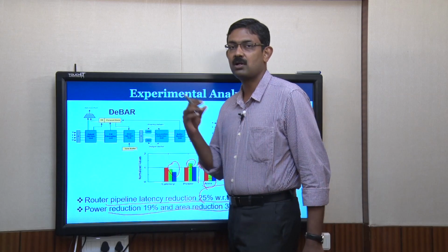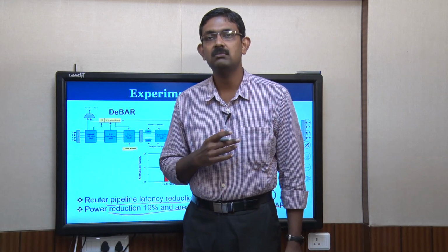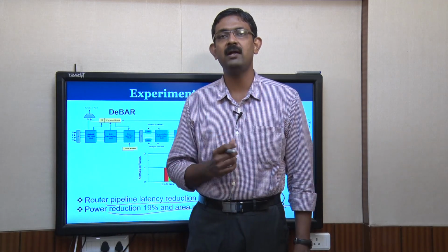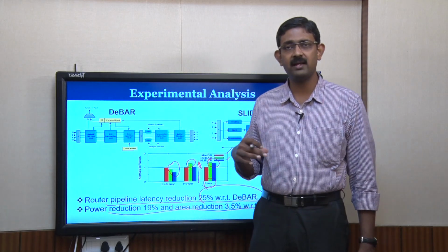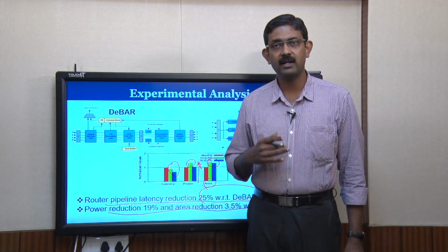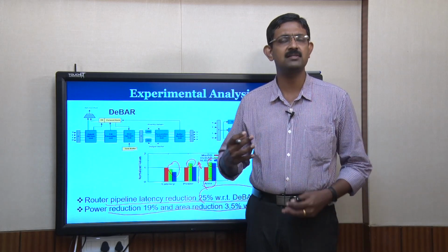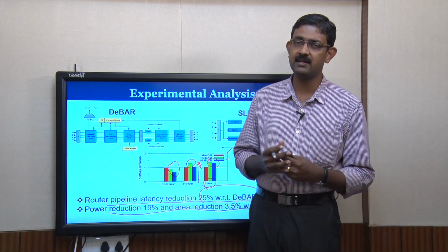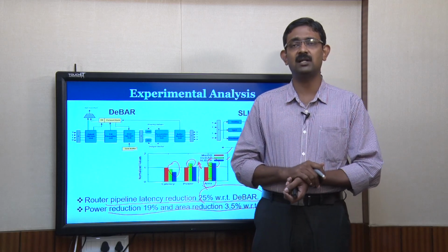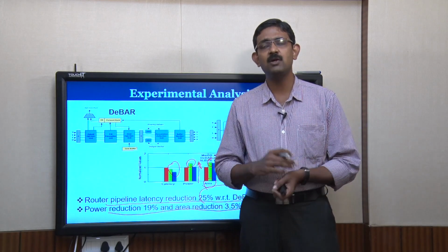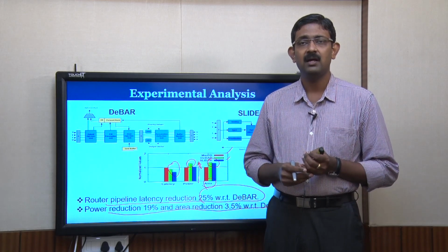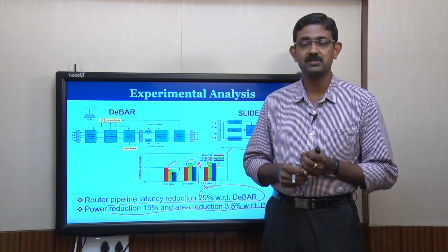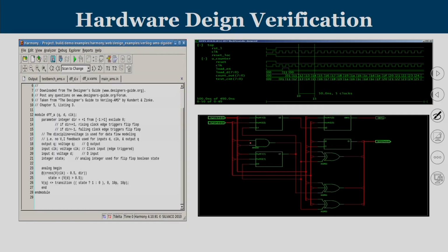So, for all these new routers for chip multi-core processors, any new idea that a researcher has has to be first modeled in a network on chip simulator like BookSim, NogSim, Garnet, many simulators are there. You model them, you get the latency, average deflection rate, many parameters. Similarly, you want to know how bulky the circuit is, and that is done by a hardware implementation, Verilog synthesis of it. So, how will you typically do hardware design verification?